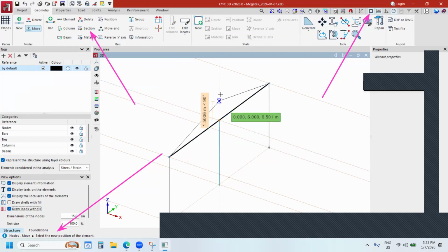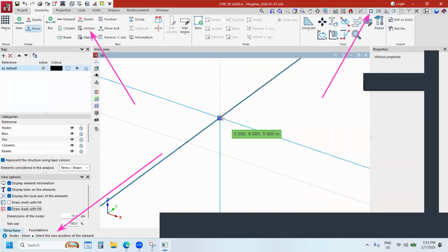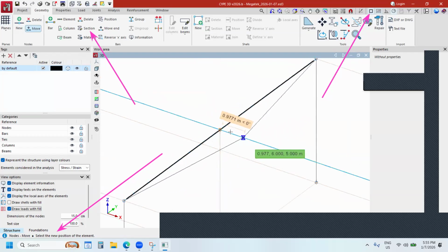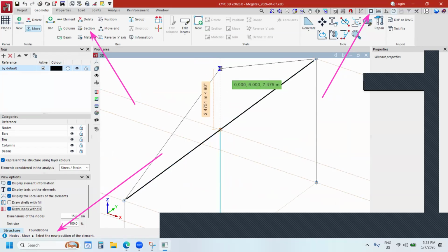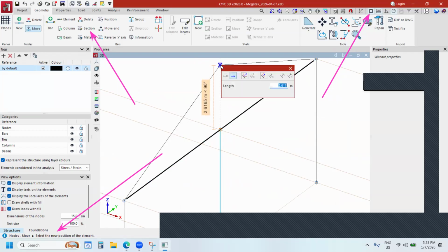You see I have the corresponding reference line to this node. Remember we said that wherever we have a node, we always have the corresponding reference lines. That's why I'm saying this reference line makes modeling easy for us. I'm not caring how far I'm going from this node. Right now it is about 2.6, but I want to go for 1.2. No worries, just click. Again, the software will ask you.